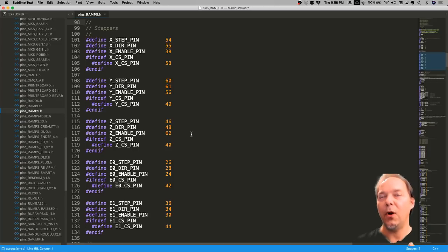Usually it's in one direction. You change to high, it does a step, you change back to low, nothing happens, but it's ready to go for the next one. And then there's a delay sometimes with the step pin, like it's on while you do the step, and then when you turn it back off low, you want to wait a certain number of milliseconds because that's expected. So that's the way those pins generally work, and you have to set them for all your steppers.